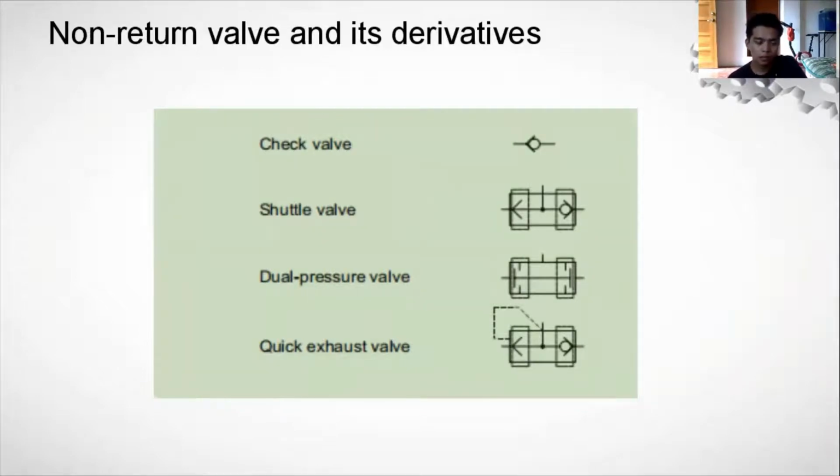So kung makikita nyo yung shuttle valve, meron siyang bilog. So yung shuttle valve ay merong dalawang input at isang output. So yung bilog, gagalaw lang siya kapag halimbawa nag-input ka sa right side input, yung bilog pupunta siya sa left side input at mabablock yun. Tapos pag nag-input ka naman sa left side, so yung bilog pupunta sa right side at mabablock yung right side input.